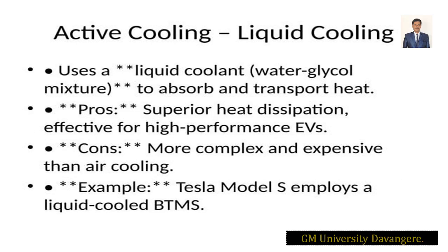Active cooling also includes liquid cooling, right? In liquid cooling you can transfer fluids across each cell to absorb the transferred heat, which can be distributed to the external environment, right? The liquid coolant can be taken as a water glycol mixture. It will pass the liquid past the neighboring cells and also beside all the cells so that cooling can happen very quickly, right? This is the coolant you have to use to reduce the cell temperature. Whenever temperature rises, you have to go for cooling. Okay, so that is one.